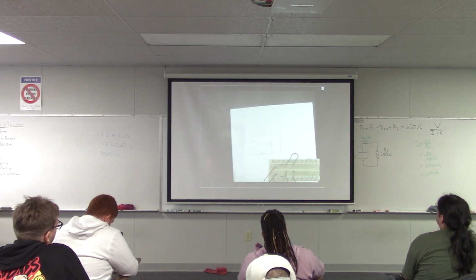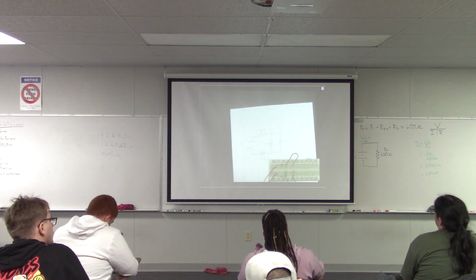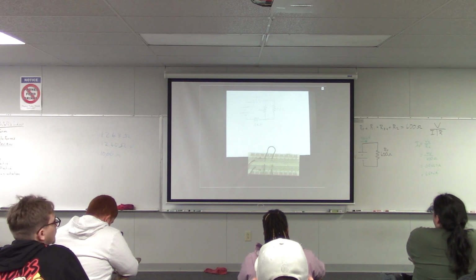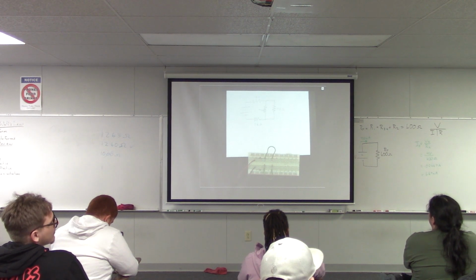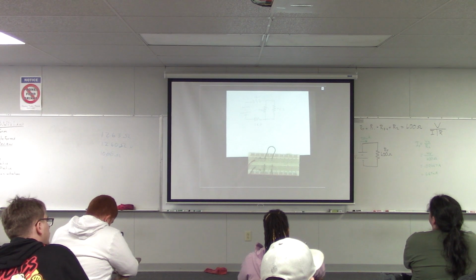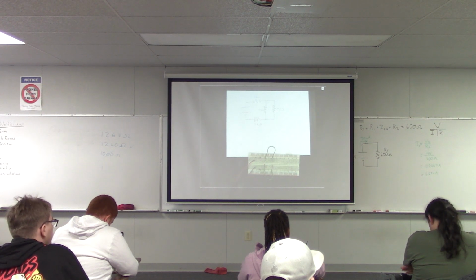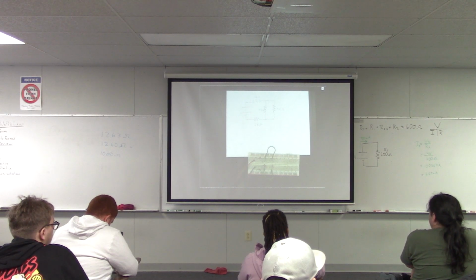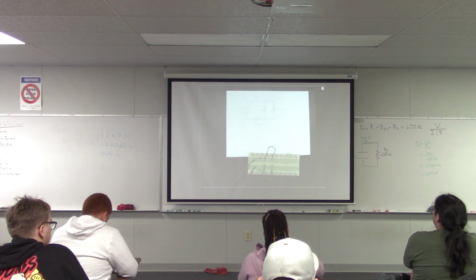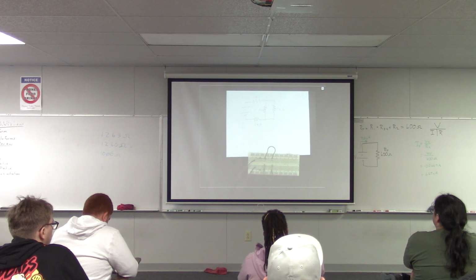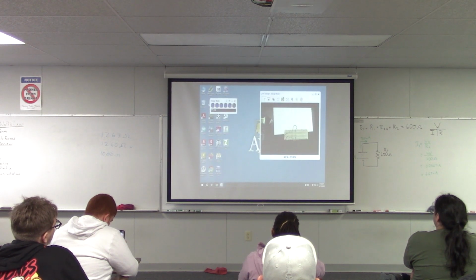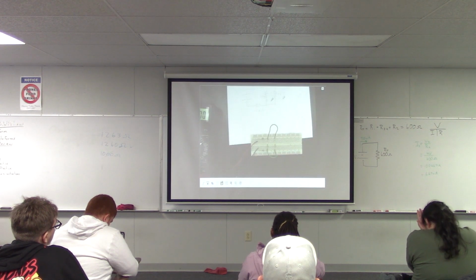Then after you do that, you can hook up your power supply, and you can start to measure the voltages and the currents. So I would measure, well, you can measure them in any order you want. If you're going to measure voltage, is that a destructive measurement or a non-destructive? Non-destructive. So remember, voltage is just in parallel. So we can just hook up.